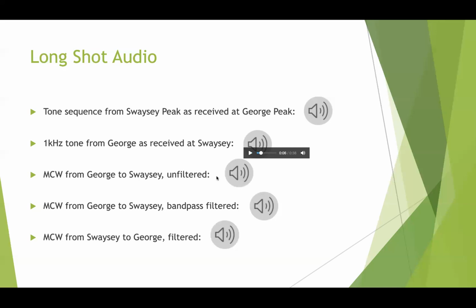So they were able to send, you guys know what MCW is, modulated CW. It's basically taking audio and putting a CW signal on an audio signal, not a real continuous wave transmission, like when the repeater IDs, that's an MCW signal. It's not real CW. They're not turning the repeater on and off while they send that. It's just modulated into that signal. So they were able to send some modulated CW.